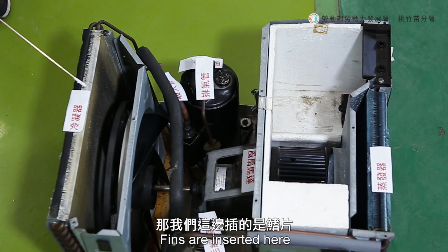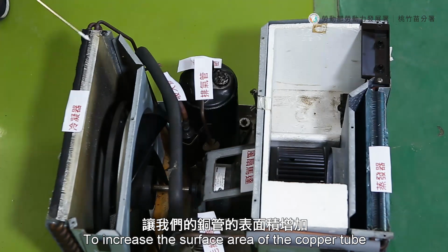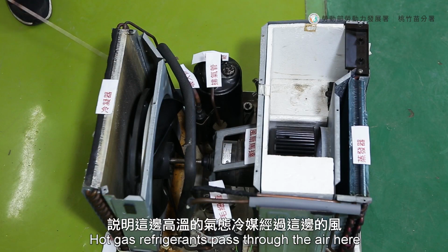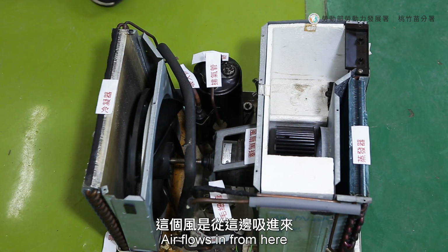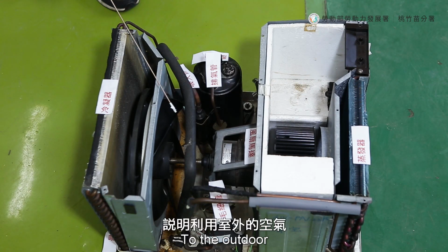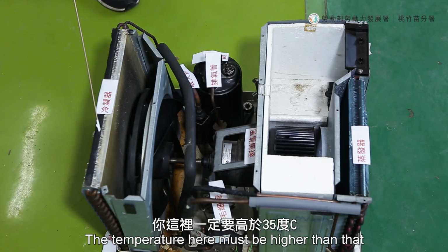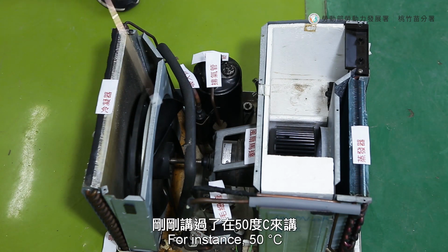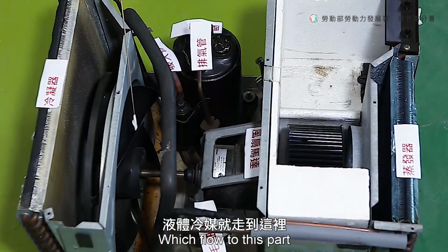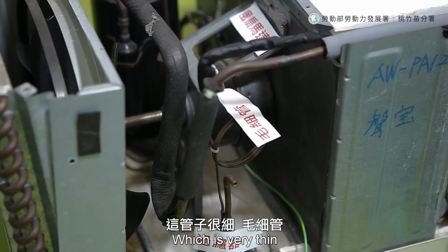Fins are inserted here, connecting to the copper tube to increase the surface area of the copper tube. So dirty fins would compromise heat dissipation. Hot gas refrigerants pass through the air here. Air flows in from here and flows out this way to the outdoor. The outdoor temperature in summer is 35 degrees. The temperature here must be higher than that. For instance, 50 degrees. Refrigerants at 50 degrees dissipate heat, and after it turns into liquid, it flows to this part, passing the capillary tube, which is very thin.